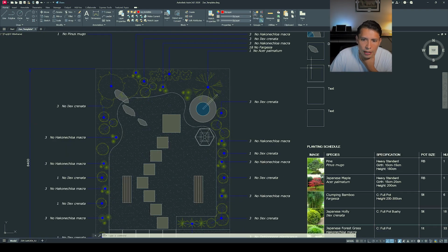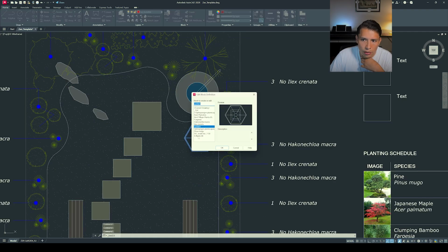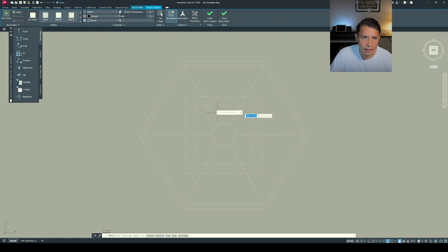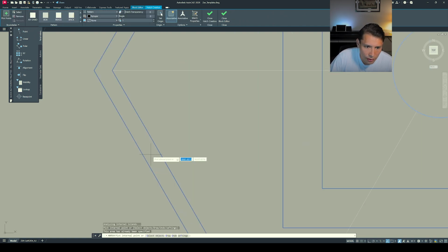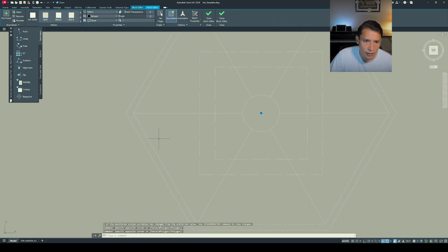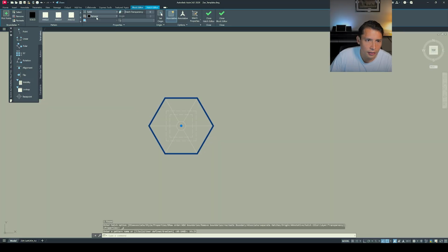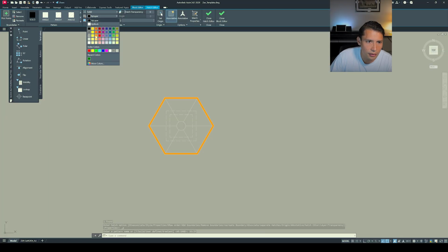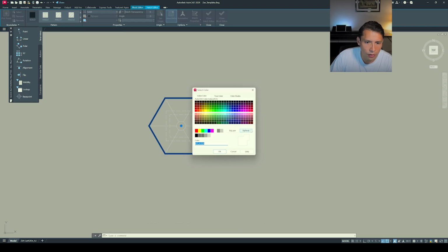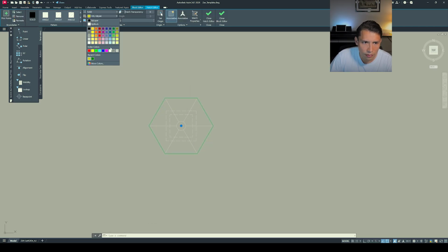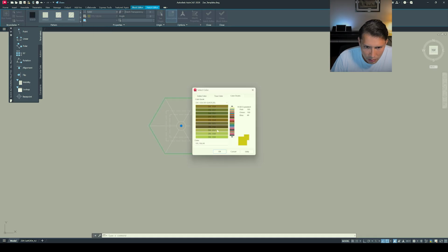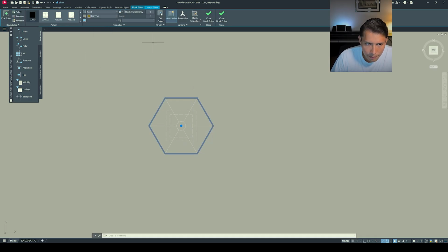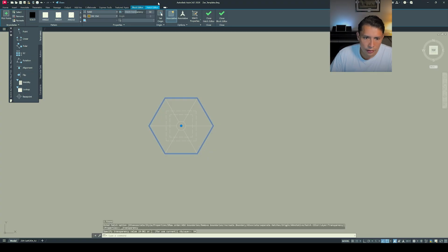So before we bring the lantern here, I'm going to double click and open the block, and I'm going to apply some basic hatches all across this inside. So let's change that to solid, and let's go for more colors, something like, doesn't look right, probably let's get this brown right here, and let's change the transparency and opacity to 50%.